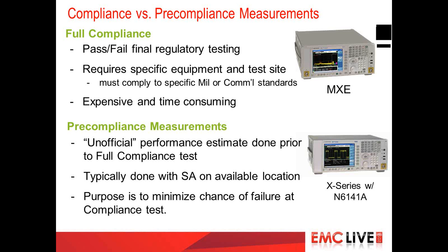And really, this shouldn't just be a one-time deal. It should be an ongoing process throughout the design cycle. If you were to wait till the very end and you have issues, things tend to be very expensive to fix. Typically, pre-compliance measurements are done with a spectrum analyzer on location. Spectrum analyzers tend to be less expensive than EMI receivers, so that's why they're used. And then on location, this could be a conference room or a parking lot. These are generally more available than multi-million-dollar EMI chambers.